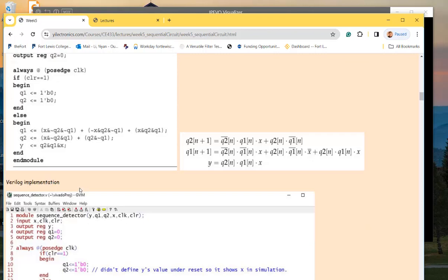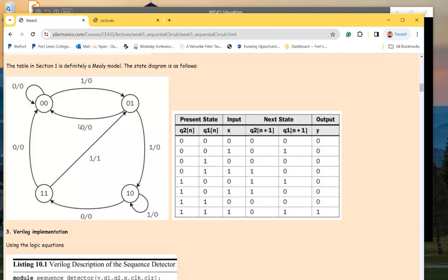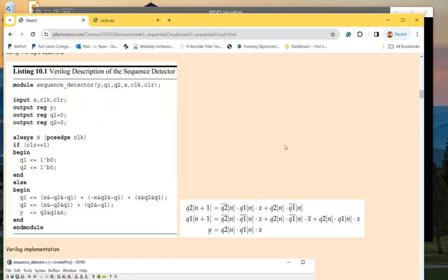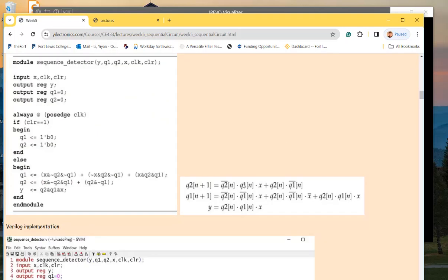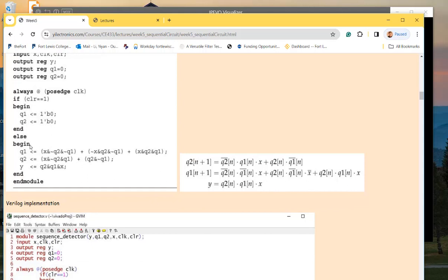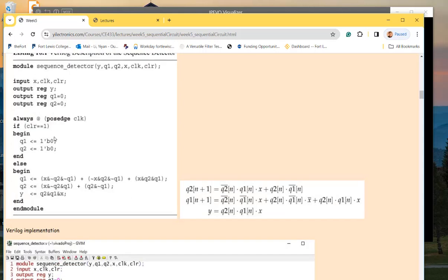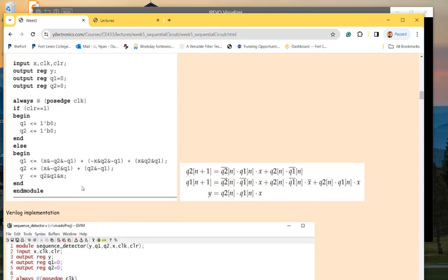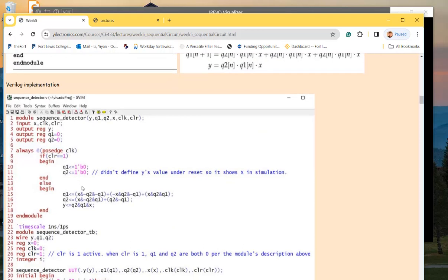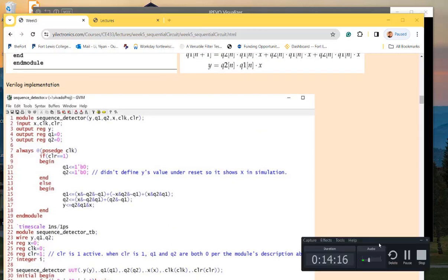But now we are doing Verilog on the Basys 3 board, so eventually they'll be synthesized by the FPGA, so you just code it up. Okay, so 3 steps. First step, find out the state diagram. Second step is the truth table. The third step is logic expression, and then directly code it up in Verilog and synthesize it, right? Make sense? Okay, that's everything I want to talk about.